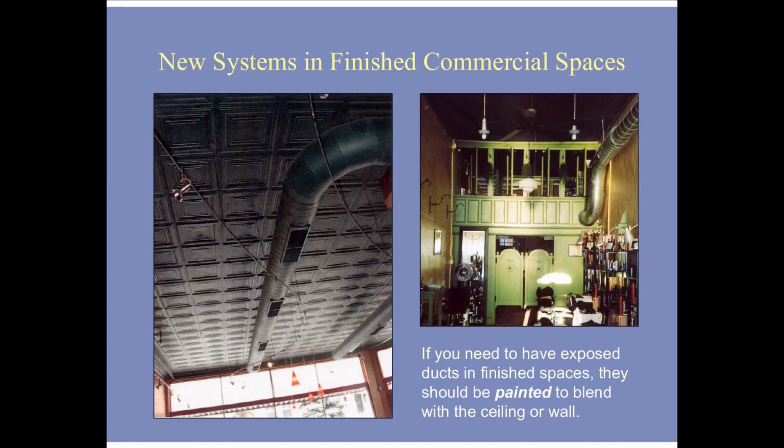In some cases, it is acceptable to use exposed ductwork in finished spaces, primarily only in commercial spaces where a soffit would obscure or damage a historic feature or finish, such as pressed metal or woodwork. Where ducts are exposed in finished spaces, they should be painted to reduce their impact on the historic interior space. As you can see in these images, because the unpainted duct on the right reflects the sunlight coming through the storefront, it is more attention grabbing than the painted duct on the left.